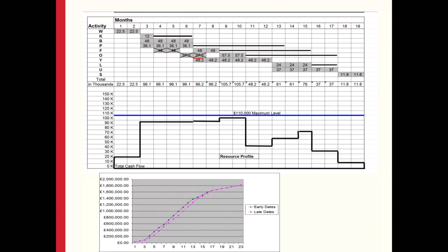Students were encouraged to think that we could use the information of the cost spent to draw our project progress curves. I think we will be discussing these in the project monitoring and control lecture in more detail, but we could plot our project S curve based on the early dates and the late dates, and these are also called banana curves. The focus during project execution is to ensure that the actual progress remains within this curve.